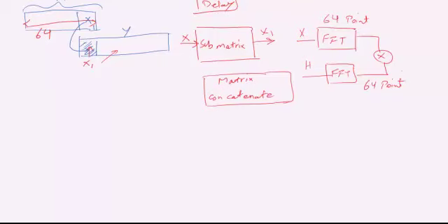And then at the output, you need to take the inverse FFT. Luckily, Simulink has another block called IFFT, or inverse FFT. You can configure that to give you the inverse of the FFT.